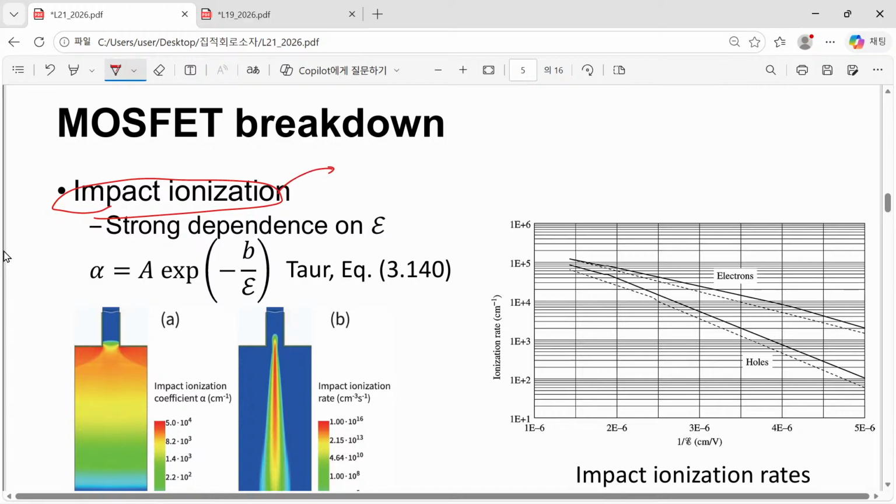Even today, I told you that when we have hot electrons whose kinetic energy is larger than the band gap energy, then it can contribute its excessive kinetic energy to the silicon structure, and one of our valence band electrons can jump into the conduction band.